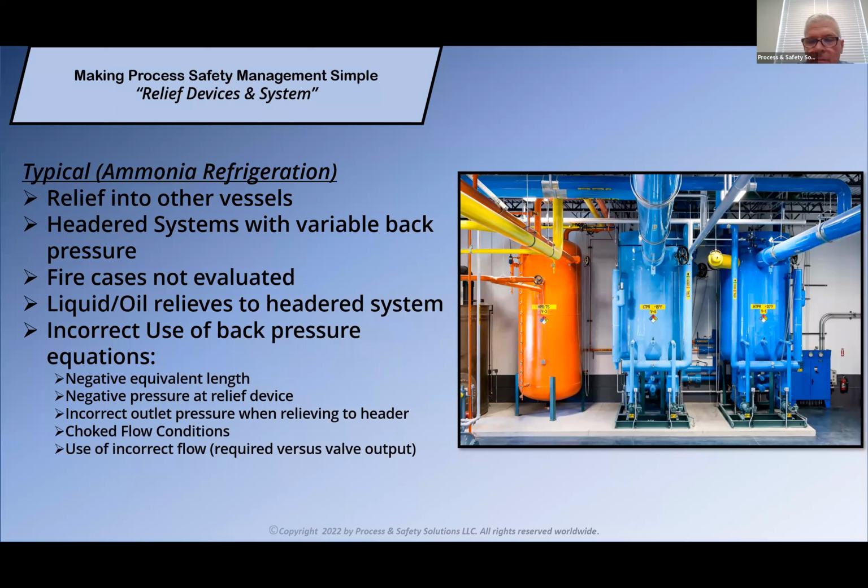For example, if you have oil relieving into your relief header, then since oil is not going to evaporate off, it's just going to sit in there, it's going to affect the performance of any relief valve downstream of that, and eventually you could affect all relief valves if it's going into a headered system. So oil, things like that should not be going into the headered system.